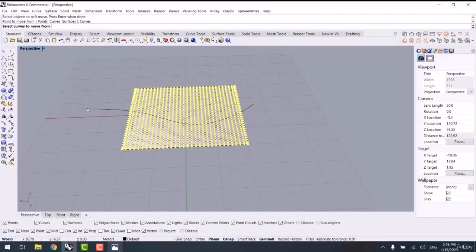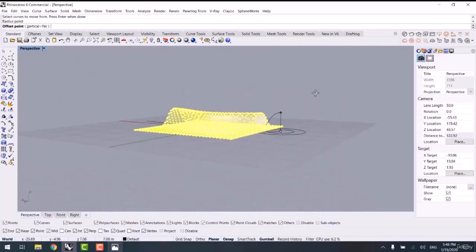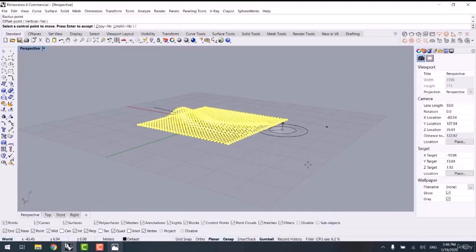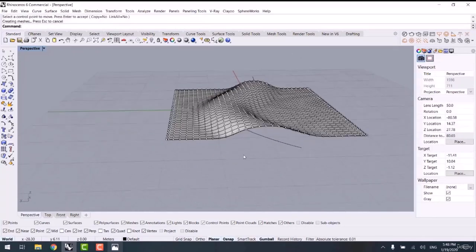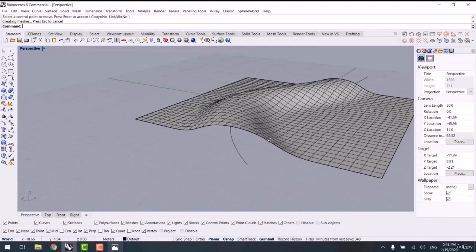The fall-off is applied radially along the curve, creating a tube-shaped volume where the move is active. And then the radius of influence. For instance, this way, I pick the radius, and then the offset point. Check it out. Okay, this is enough.